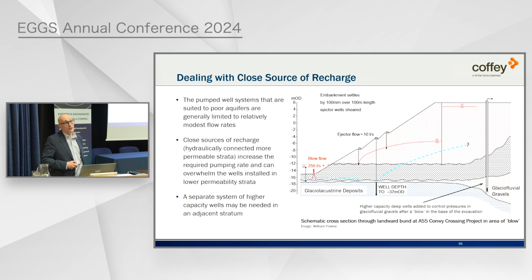My talk next week on the Kilsby tunnel is about a glacial channel in the 1830s that caused big problems. And once you know it's there, once you've picked it up and you've got your model, then you have to directly dewater it. A small number of very high capacity wells were installed here, and they depressurised it and dealt with it in that way.